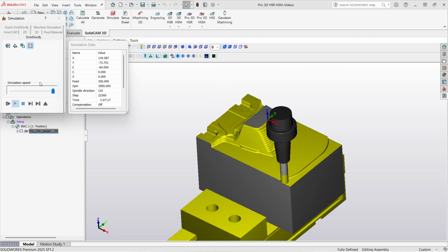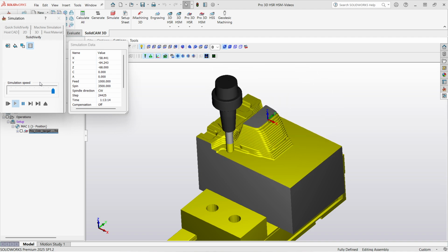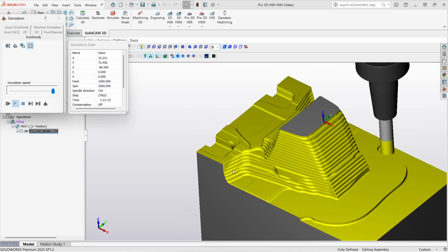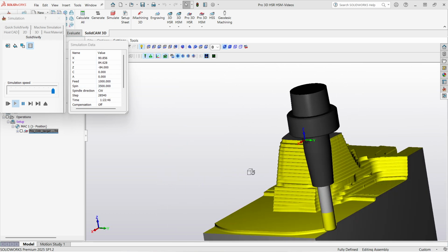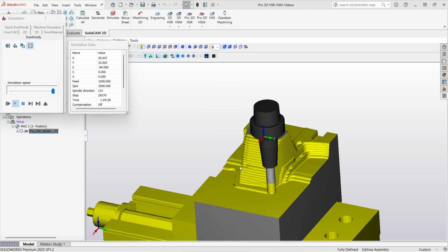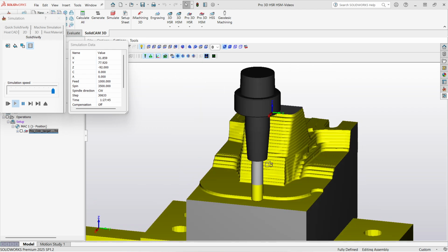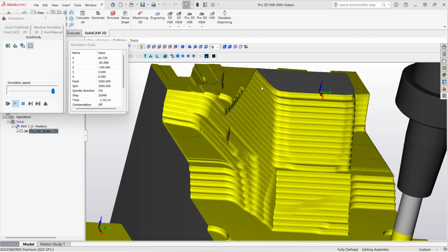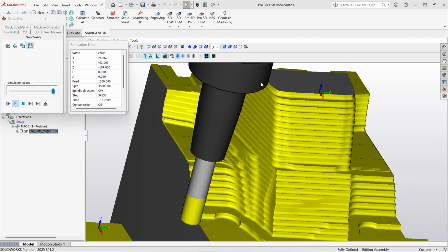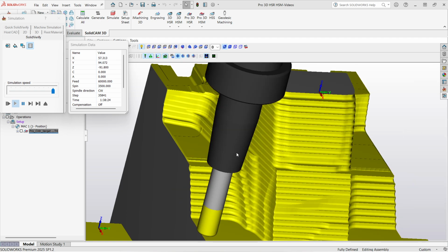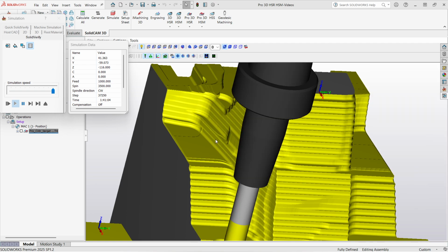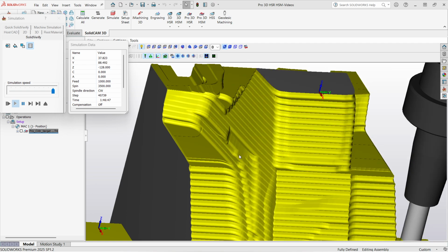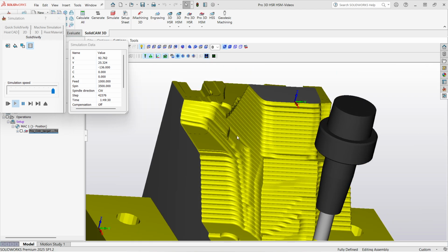So basically, SolidCam keeps the tool away from the in process stock for each element of the tool. You can see it clearly here. When the arbor is colliding in this portion of the stock, it just shifted the tool away from this wall so that it can avoid that gouge.